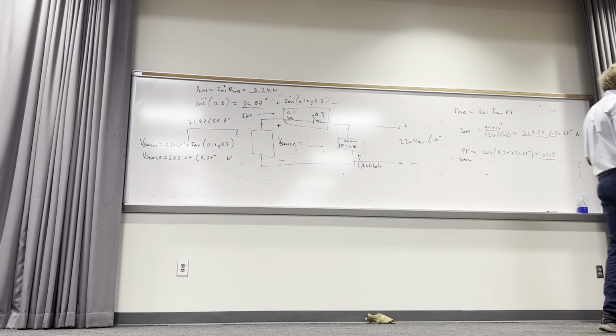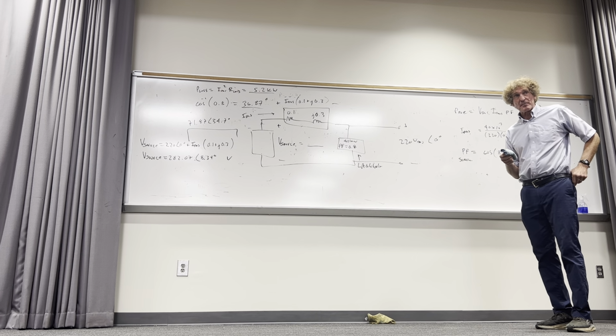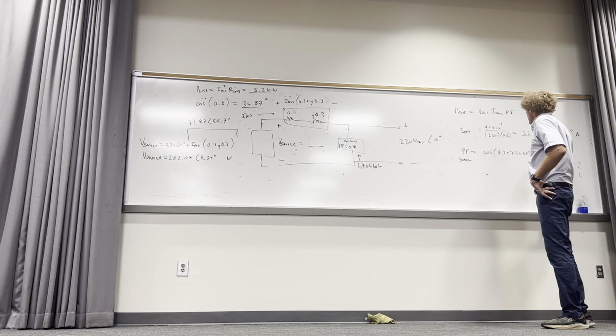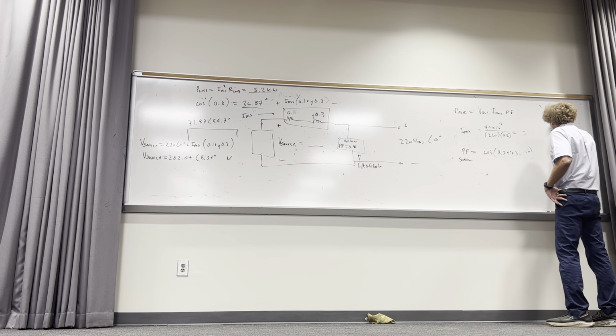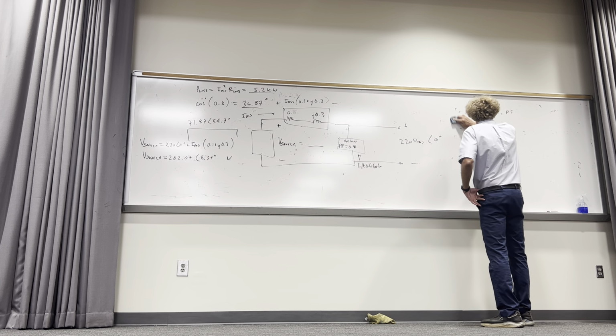And I don't really know anymore. How many mills do we have around here? Do we have any large industry around here that does any kind of rotating machinery? Well, we have some automobile assembly lines and stuff. They may use some of these things, but we don't have the mills that used to have the big problem, because mills typically, they're all inductive motors, and it takes a lot of money for the capacitor banks to correct that.